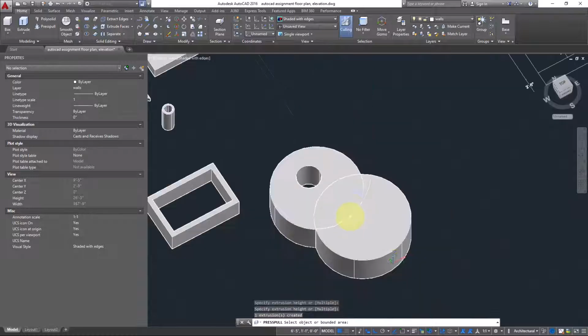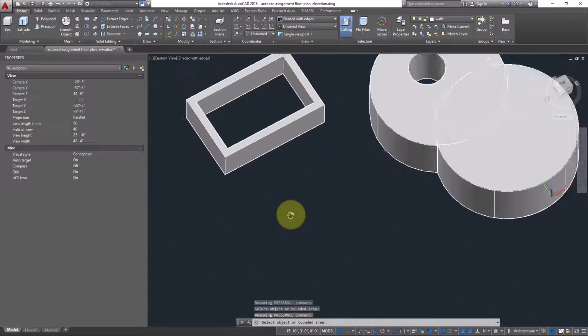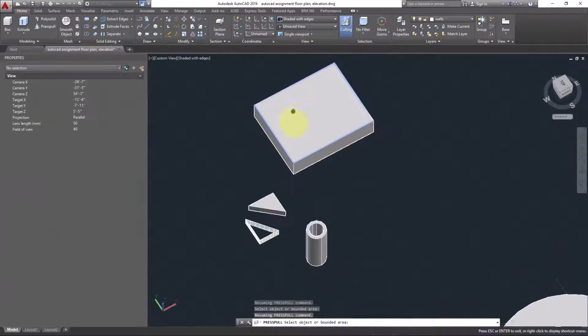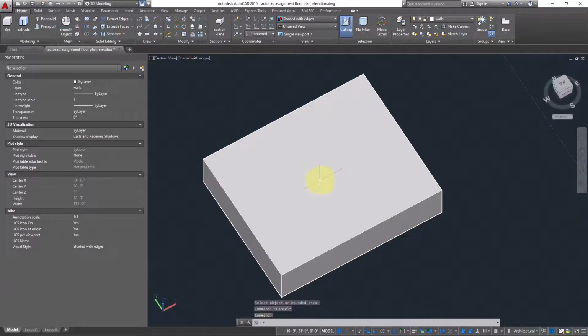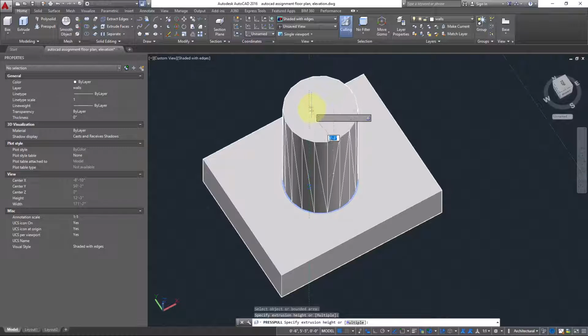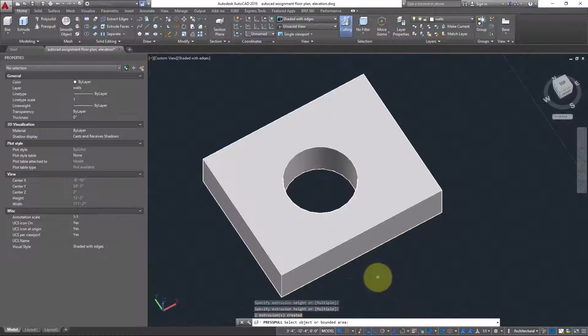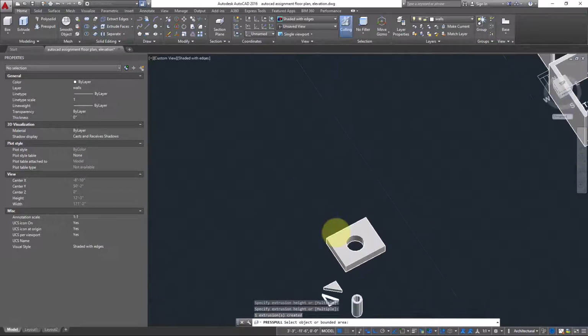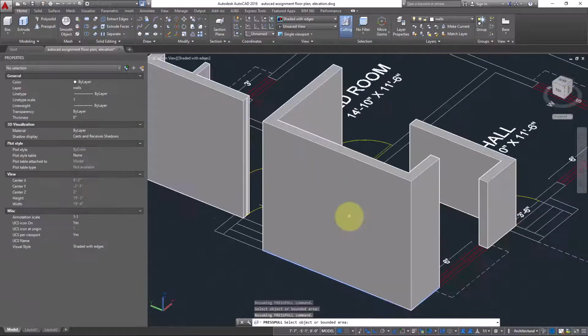If you want to create a hole in any surface, you can also do that. How will we do that? For example, here you want to create a hole. For that you need to create a circle on it. Just create a circle like this. Then take Presspull, and if you click and drag upward, it will add material. If you drag downward, it will remove material. So you can also use this to create holes. Even some people use this to create windows, window space.